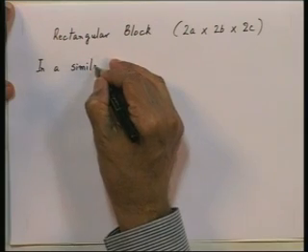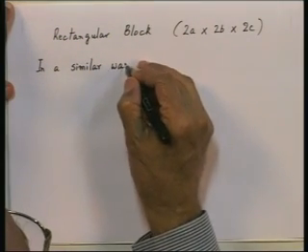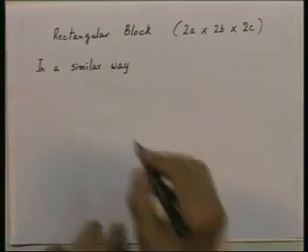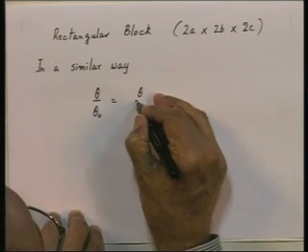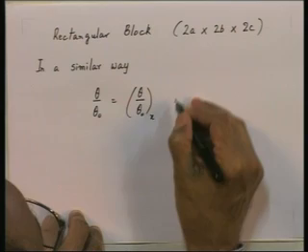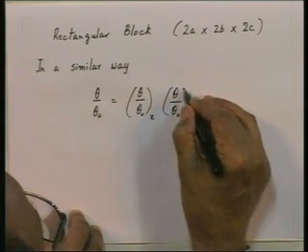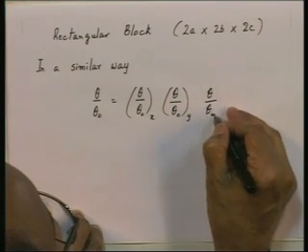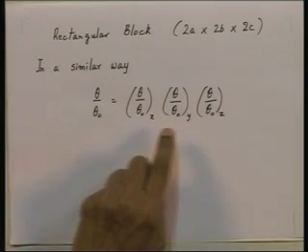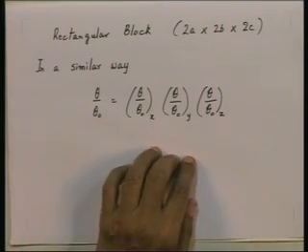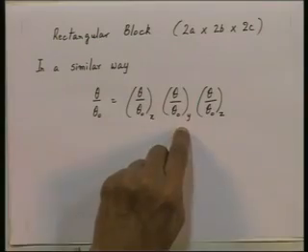And interestingly enough, in a similar way, the solution for this case has been obtained to be theta by theta naught equal to theta by theta naught x multiplied by theta by theta naught y multiplied by theta by theta naught z, where the three quantities on the right hand side are the solutions for infinite slabs of width 2a, 2b and 2c, which we can obtain from the series solution I have given you earlier.